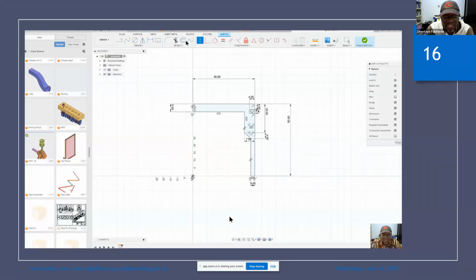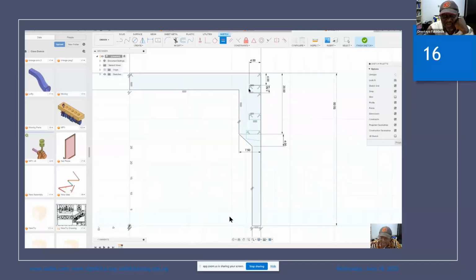And then you are going to take the equality constraint. You take the equality constraint and say, well, I want this line and this line to be equal. So whatever that is 4, so that one will be 4. So you use the equality constraint when you need to, instead of, that is 2.5, so that is 2.5 also. And then what else? The distance from that point to the next point is 2.5. Okay. So the horizontal verticals again.